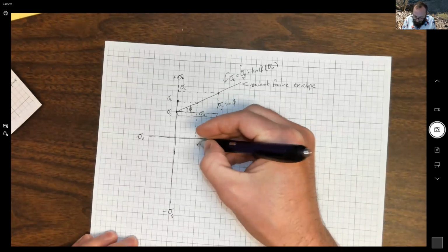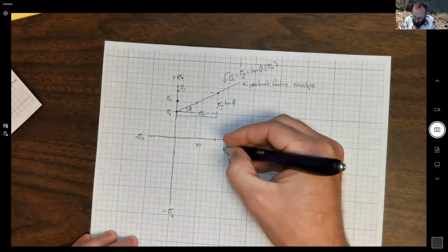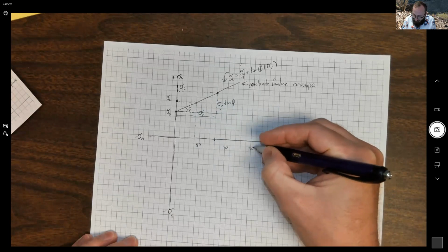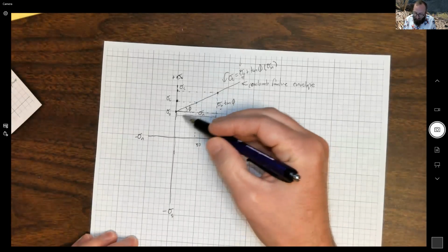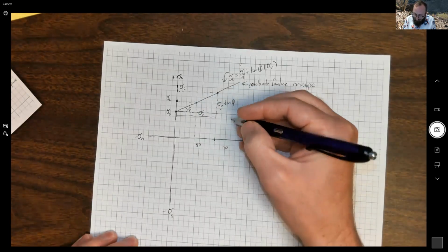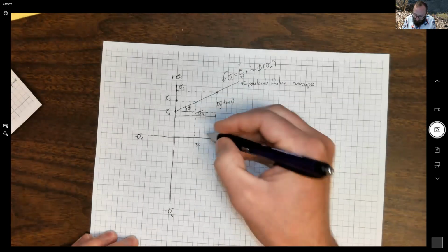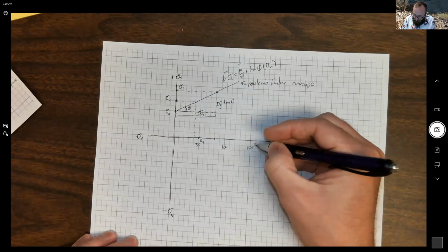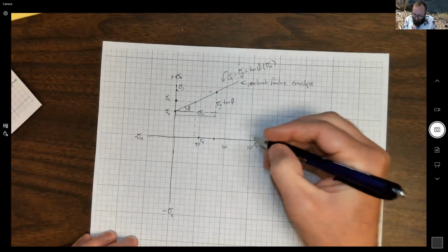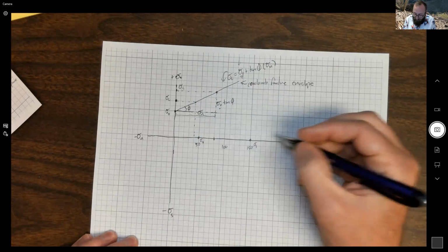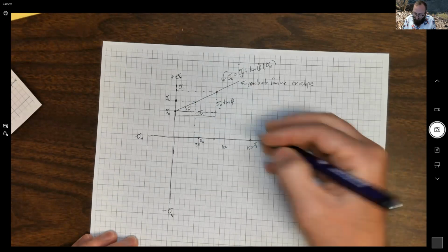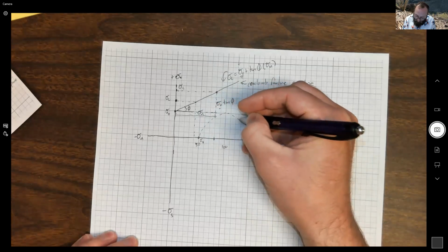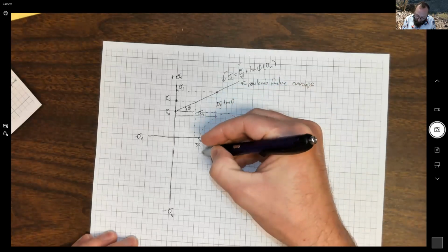Okay, so say we have, let's say this is 50 MPa, 100 MPa, 150 MPa. For this particular failure envelope I've drawn here, if we had a confining stress, sigma 3, of 50 MPa, and a maximum principal stress, sigma 1, of 150, our circle, if I could draw a perfect circle, would look like this.